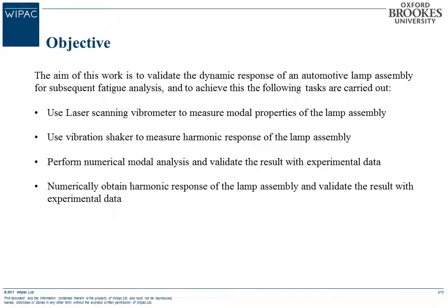Objective: in order to validate the dynamic response of an automotive lamp assembly, the following tasks are carried out. Measure modal properties of the lamp assembly using a laser scanning vibrometer. Use a vibration shaker to measure harmonic response of the lamp assembly.